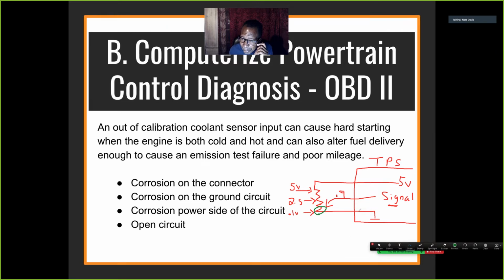But now if I have an unintentional resistance in the circuit, which is this one, I got to push the current through this and this. In order to do that, I got to increase the voltage requirement to get higher. So that signal line voltage will go up. Does that make sense? Yeah, it makes sense.